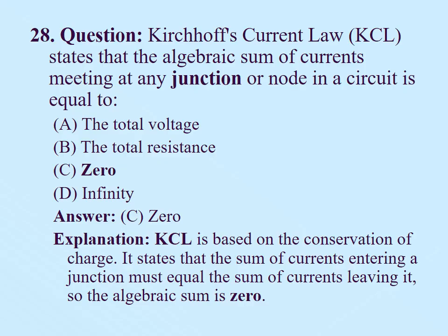Kirchhoff's current law is based on the conservation of charge. It states that the sum of currents entering a junction must equal the sum of currents leaving it. So, the algebraic sum is 0.